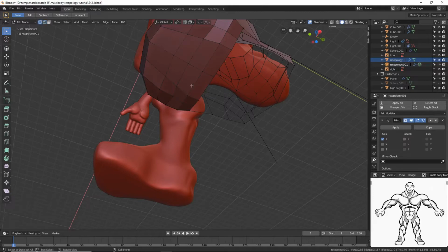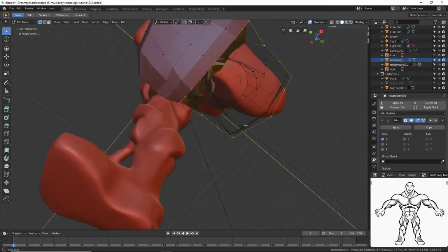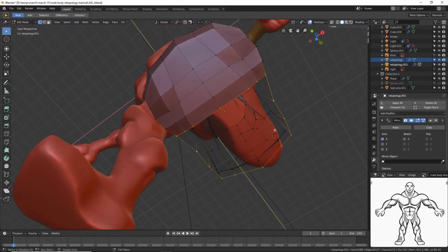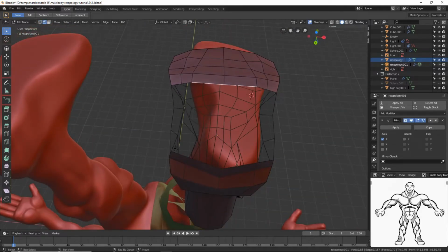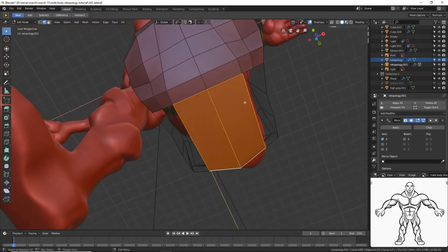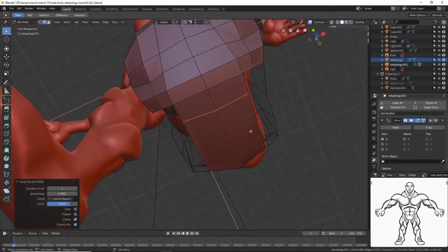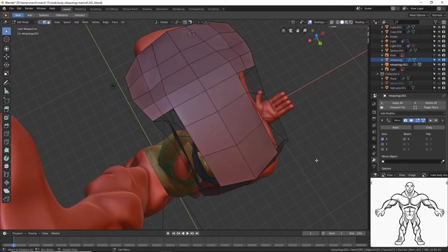So we're going to go to vertex select, hold alt, left click here. We have 9 faces here. So what we're going to do is click there, hold shift, click here again, press F to fill. So there's a line here, so I'm going to hold control, press R, left click, hold control, press R, left click here to deselect.